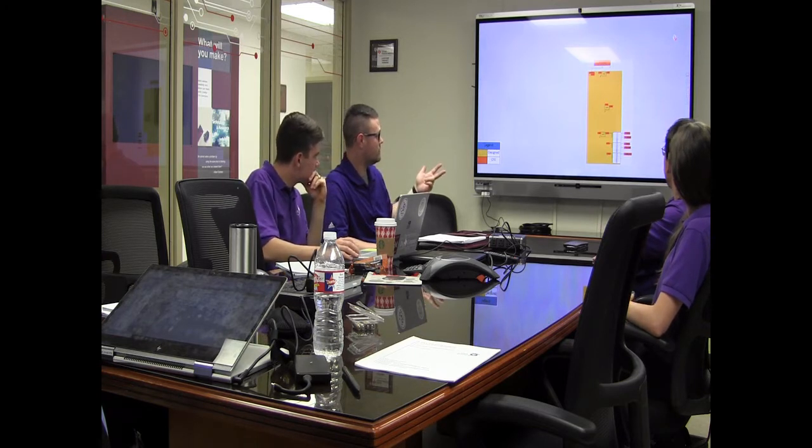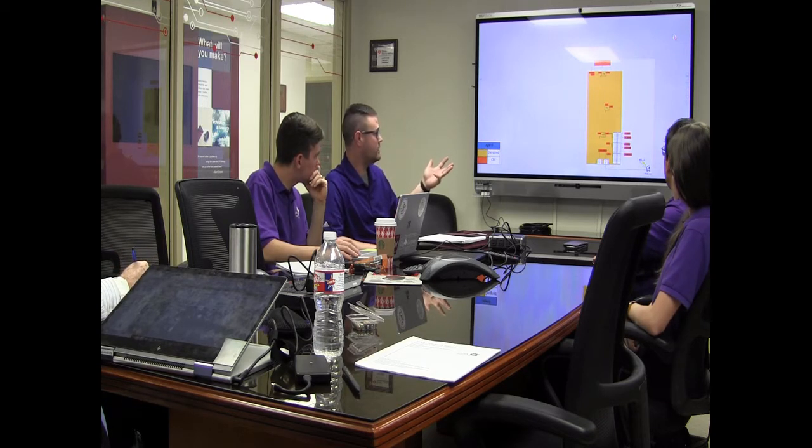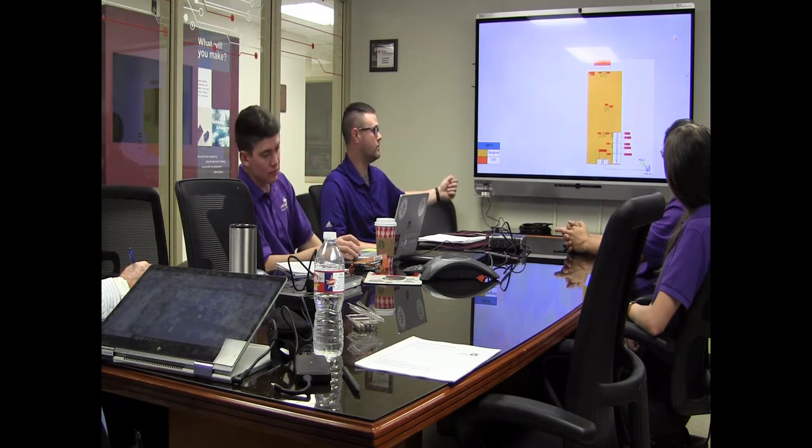The hotspot runs off of the 12 volts off one of our boards, and then the PCA9685, which is a PWM controller that we'll see in a second, runs off 5 volts that we regulated down, as well as the USB charging ports. So we've got the Wyze Cam connected directly to one of the USB charging ports in every room, not in the basement because there's no camera in the basement, and the cameras that are outside of the house, we actually have 2 of them. We've got a static cam and a movable cam. The static cam is the one that we saw that cool time lapse on, and the movable cam is just recording and live view. So you can see both.